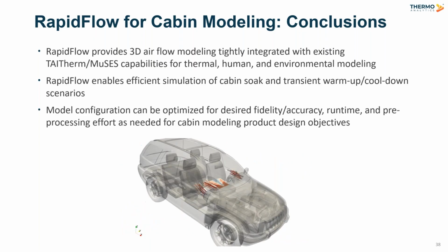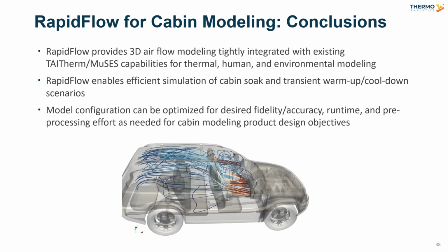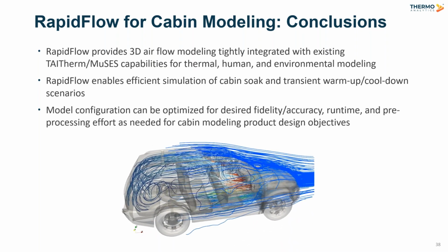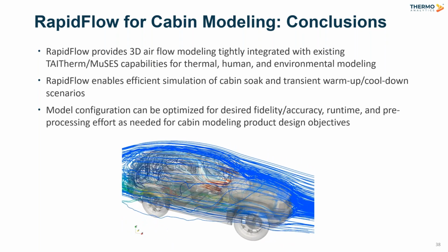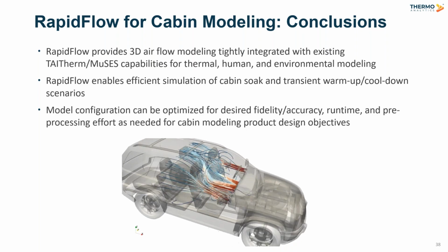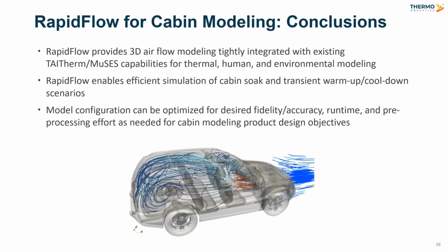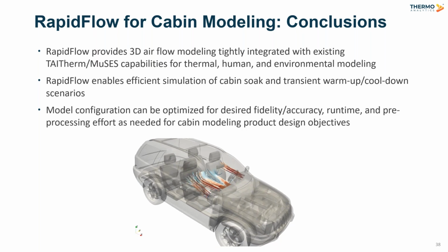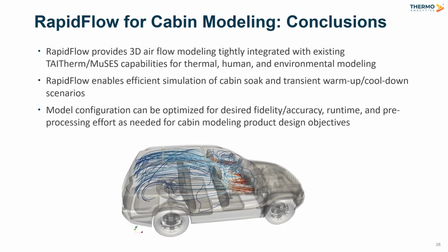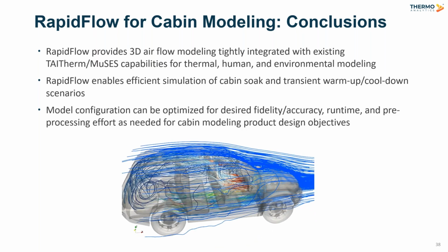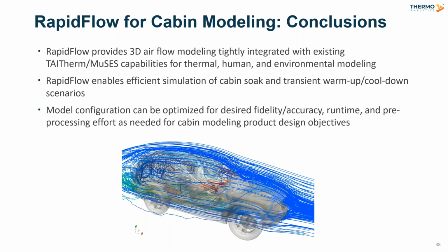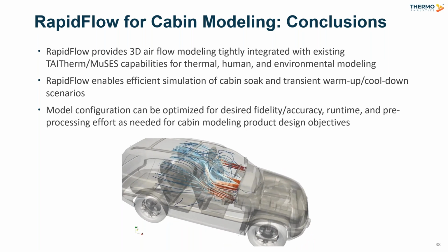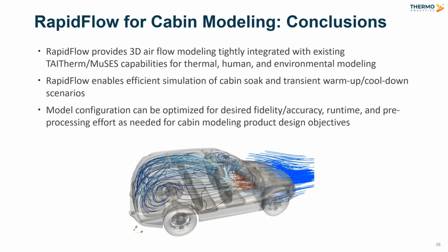So because of those simplified flow equations, we're not bound to something either like a wall function or a resolved boundary layer method that you would see in more conventional CFD. And as a result, there are not really any constraints on how fine or coarse the mesh needs to be near the walls.